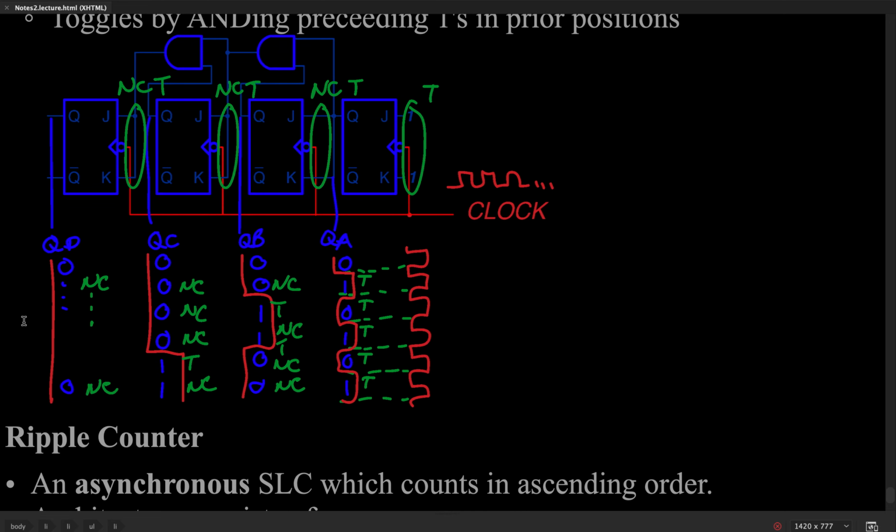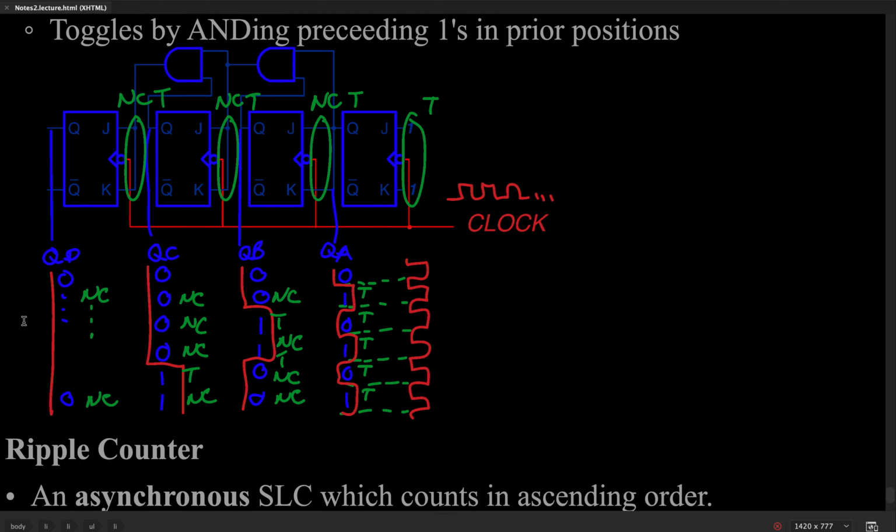By the way, as I'm bringing this up, you might want to ask, you did build a counter in the laboratory. It was just 2 flip-flops, actually. What is the meaning of all these things, and where is the read-only memory? Well, the read-only memory is how they build counters now, especially because they can be very long. It's 32 bits, 64 bits. But initially, when the counters were designed, they were built from gates, and it was efficient to do that. And we're showing that example here. So there's no read-only memory in this design.